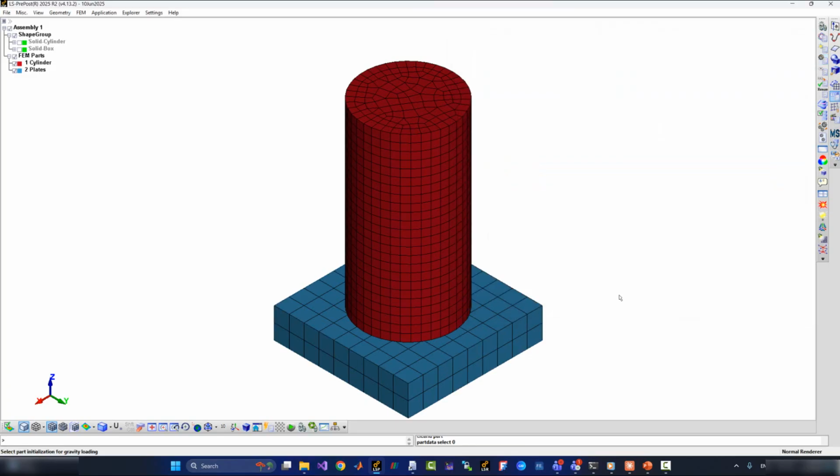Now the next thing that I'm going to do, again, we could take the path of drawing an extra solid box and then discretize it, generating a mesh for that extra solid box. Instead, I'm going to follow a different path. I'm just going to copy the assemblage of elements that I have created, this blue assemblage for the bottom plate, and create a single copy of it at the top plate, which must be at a vertical distance of what? 12 inches the cylinder height plus 2 inches the thickness of the plate. It must be copied along a distance of 14 inches in the Z direction.